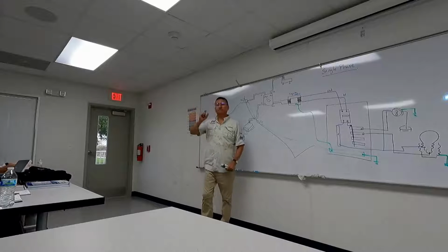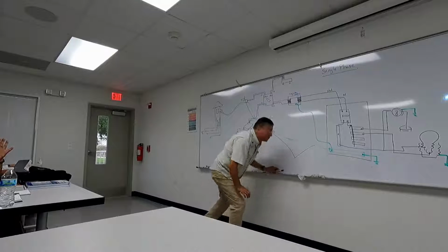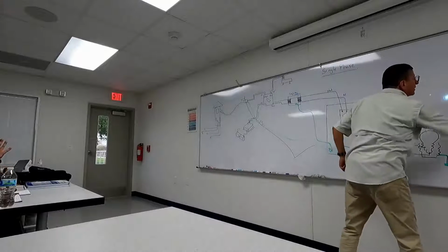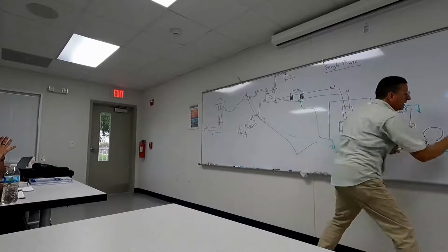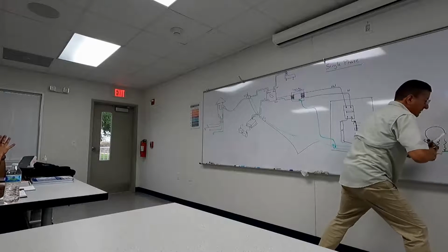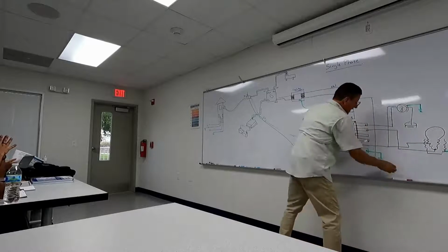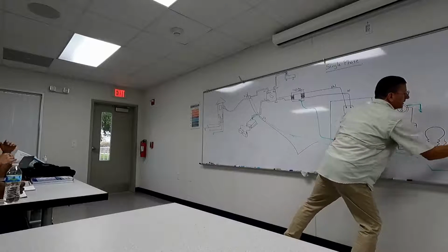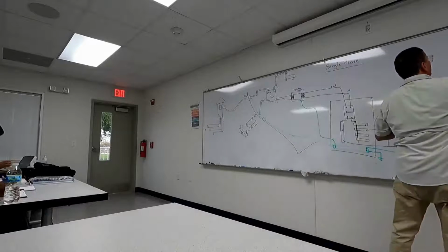Guys, let me explain something. You remember the previous picture on the screen? This is the bonding conductor, and the bonding conductor is connected externally with a wire to the piece of zinc. And look, the negative bus bar is connected, and the ground bus bar in the AC panel, to the bonding conductor. No? Bonding conductor.